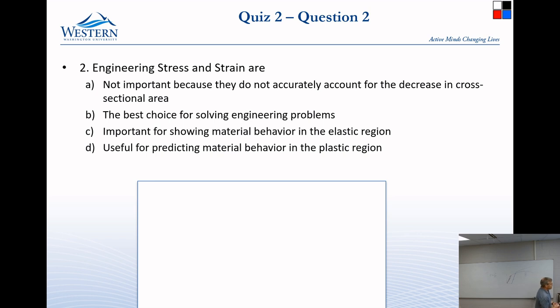And so that happens. So is it useful for predicting material behavior in the plastic region? It is, as far as giving you the ultimate tensile strength. Beyond that, it's a bit of a misnomer. So it's better to use true stress, true strain. But we don't very often. Why don't we use true stress, true strain very often?